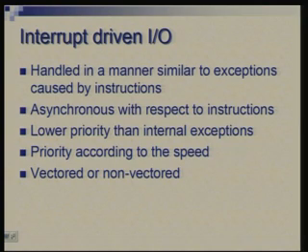Here what we do is we allow a device to inform the processor about its readiness. So, the processor will instruct the device and ask it to send an interrupt or send an exception as and when it needs processor attention.